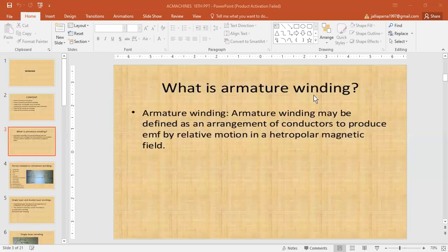The group of wires or conductors constituting a coil set of a multi-turn coil is wrapped with tape as a unit and is placed in the armature slot. It may be noted that since the beginning and the end of each winding element must be connected to the commutator bar, there are as many commutator bars as winding elements for both the lap and wave windings.